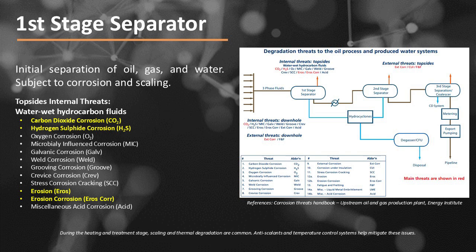Number 10 is stress corrosion cracking, or SCC. A combination of tensile stress and a corrosive environment can lead to cracking. This is particularly dangerous because it can occur without significant warning or visible damage.